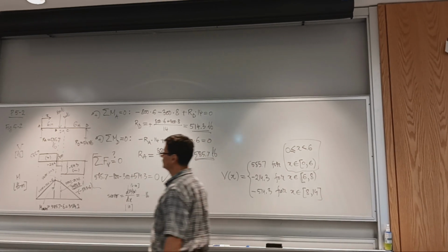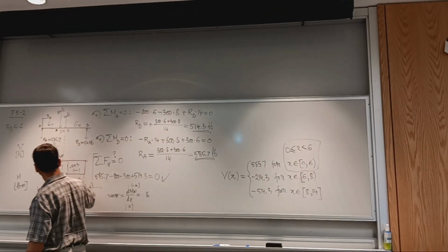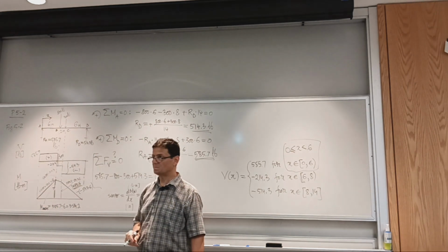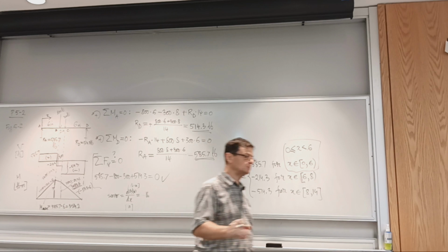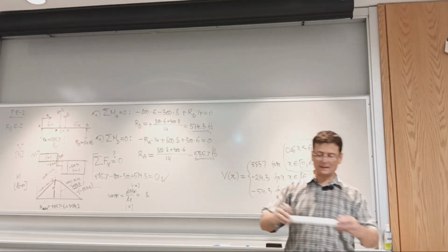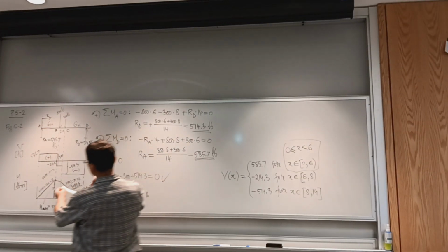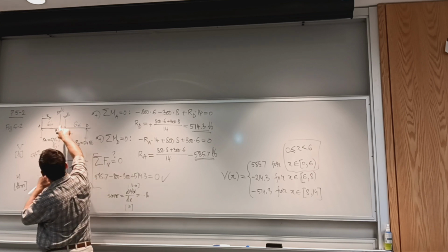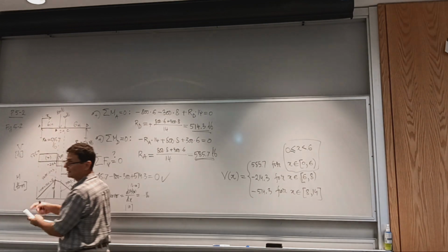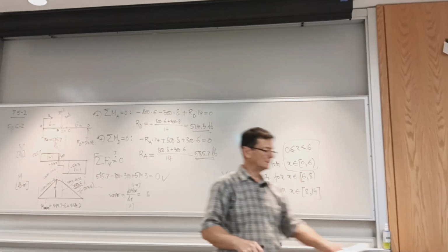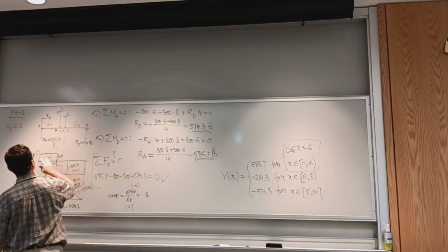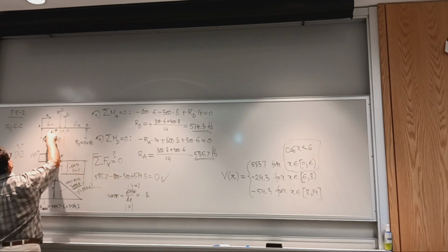So what do you do with this type of diagrams? You can evaluate what the maximum stress due to bending is. We're not there yet, but I'm anticipating. So you have the beam, and the maximum bending moment happens to be where this load is applied, and failure may occur there. You can also look for stress analysis in some locations where there's a weakness.